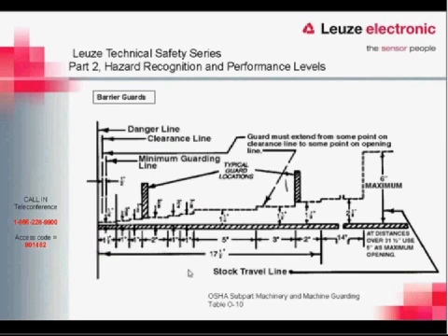So this is something you may or may not have seen. They're pretty common. It's called a gotcha stick. Lots of people make these. They're usually just handouts that safety companies give away. And it's got all of these notches on it. And basically what it says is if you have guarding in place, or maybe there's not guarding in place, if you can reach the hazard with this stick, that's not a good thing.